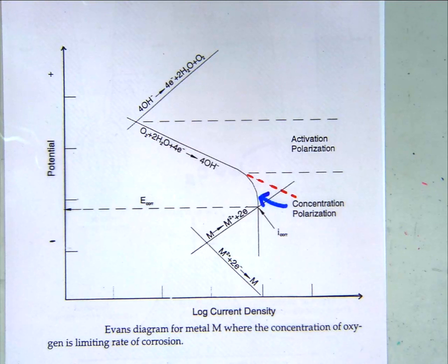Metal reaction, that's its free corrosion potential there. This is oxidation of the metal on this line, reduction of the metal on that line. And so the intercept of the anode process and the cathode process is here and gives us our new mixed potential for the cell between this metal and oxygen. It's the same concept as you've got on your handout.